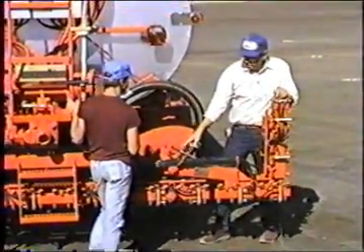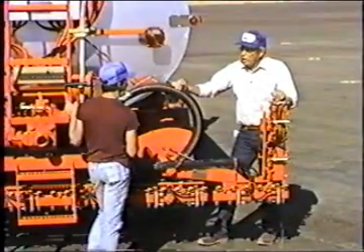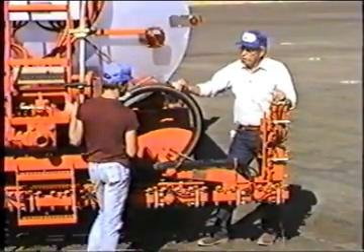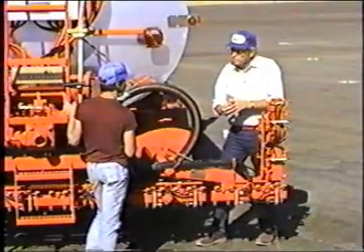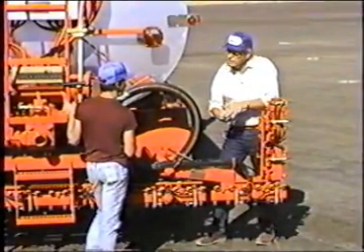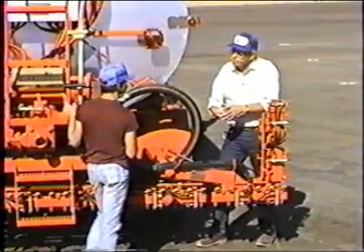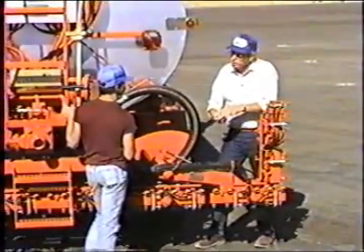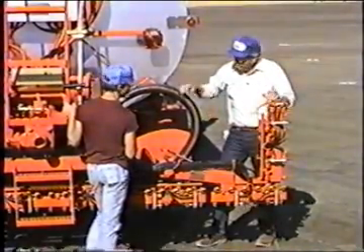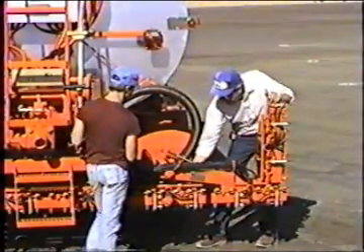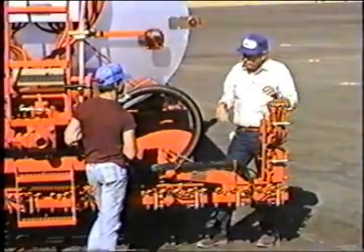The swing joint, in order to be full circulating, all these swivel joints and swing joints have to have 2 passages all the way through them. They have a 2-inch tube inside a 5-inch tube, and that gives us the internal passage and the external passage, the passage between the tubes. Around the outside of the internal tube, inside of the outer tube, is the external passage. Okay, when we come down this hose and get into the base of the swing joint, we get into the external passage.